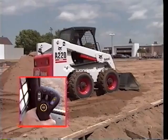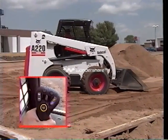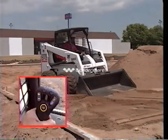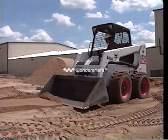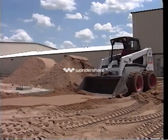The inching control reduces travel speed to half that of low range, while engine RPMs remain the same, providing the operator full hydraulic speed and power at a slower travel speed. This feature is used when hooking up attachments, fine grading, or using attachments such as a planer.